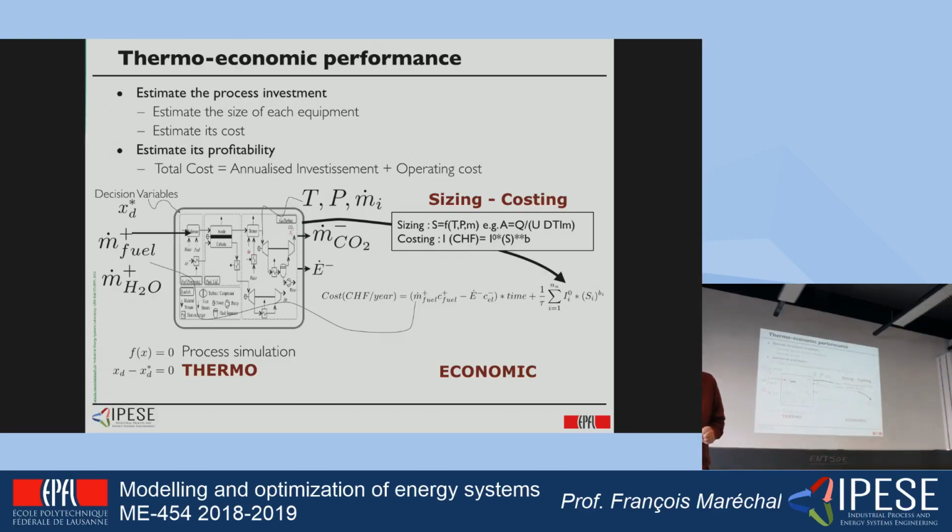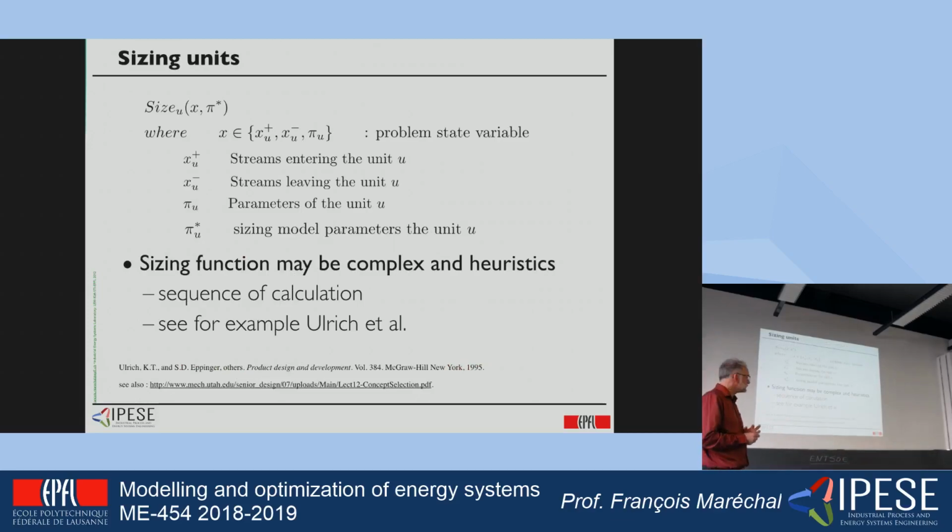So sizing the units is in fact related to the knowledge that engineers have of the principles of energy conversion in the different devices. Okay, so heat transfer for heat exchangers, compression for compressors, and typically you can have handbooks that are going to tell you, okay, if you have to go from this pressure to this pressure with this type of compressor, then you have to size it in this way.